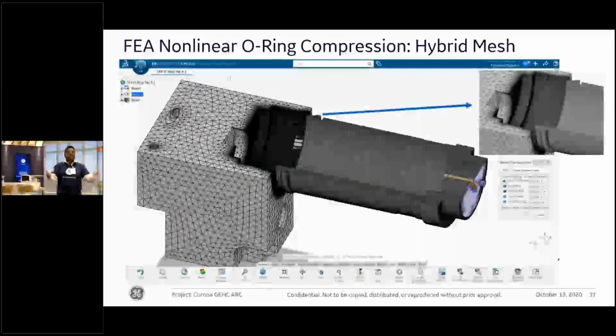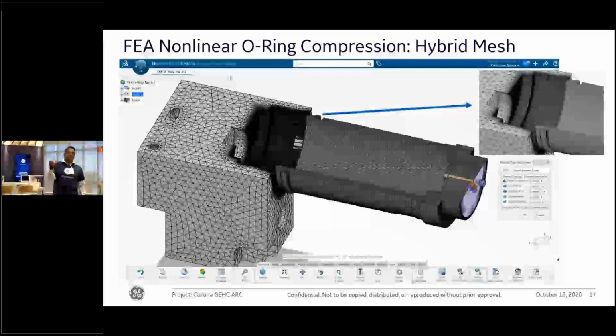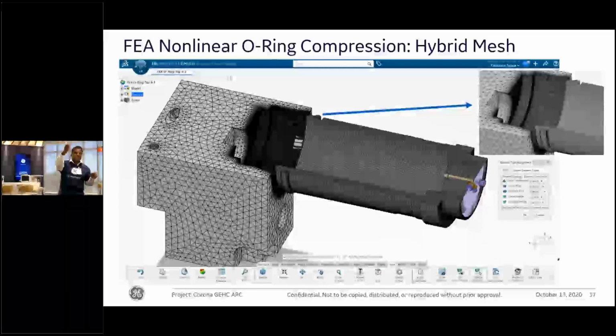And we got to have a good mesh in order to have a realistic simulation. So we love this meshing coming out of Structural Performance Engineer, Doctor. Yeah, the meshing tool here is pretty amazing. And then Dr. Joe asked me to run it on my laptop because everything is cloud-based. I'm not using my laptop. So we created around 600,000 elements, and you see the details, how the elastomer is modeled using brick elements and all the parts like metal, bottom and the top, everything we took care of with bricks as well as tetrahedrons.